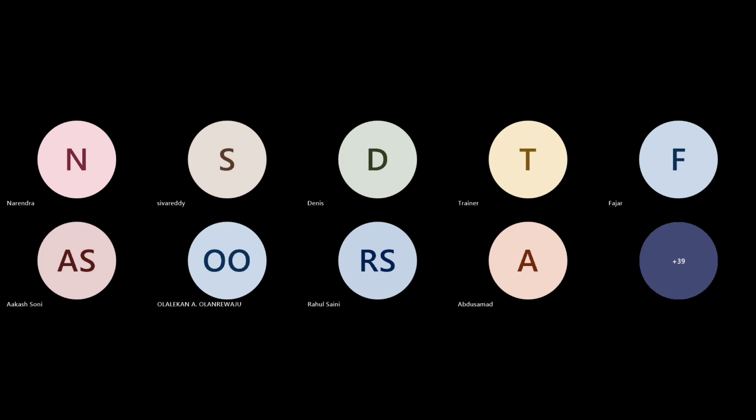Generally, we don't go into that separation because the molecules carried over are ions, H plus and O minus ions. We don't do any separation sizing for that. We know that for every molecule of hydrogen generated, there are 3 moles of water carried over along with it. So we do separator sizing to separate the water.